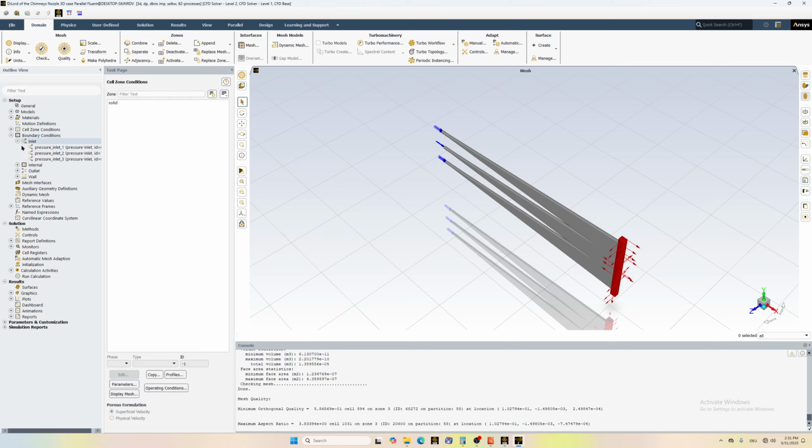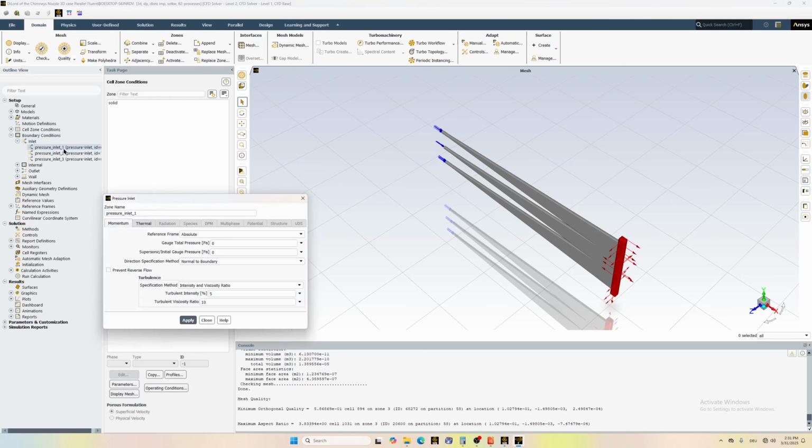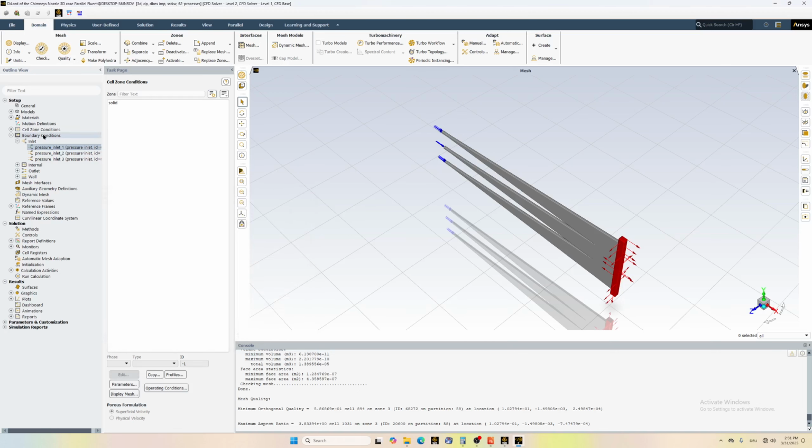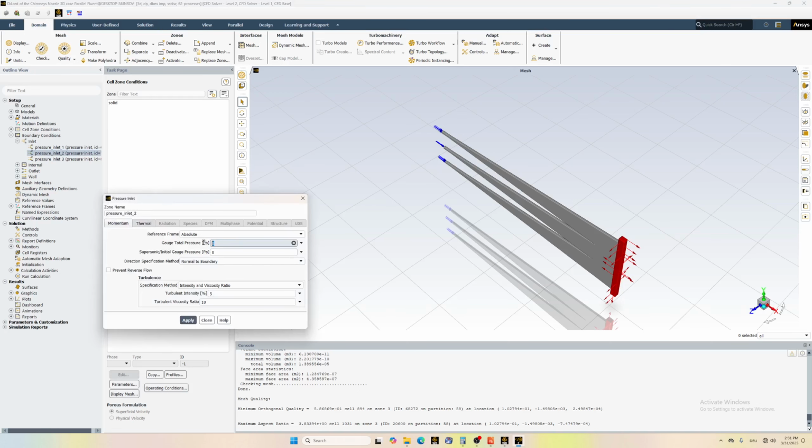Okay, now boundary conditions, we have 3 inlets, and we can define one bar or 100,000 and initial 99,000. It doesn't matter, this one just to be slightly less than this one to initialize the flow. Here I keep 5% by default. I put here a number, it doesn't really matter for this example. Read the manual how to define that thing.